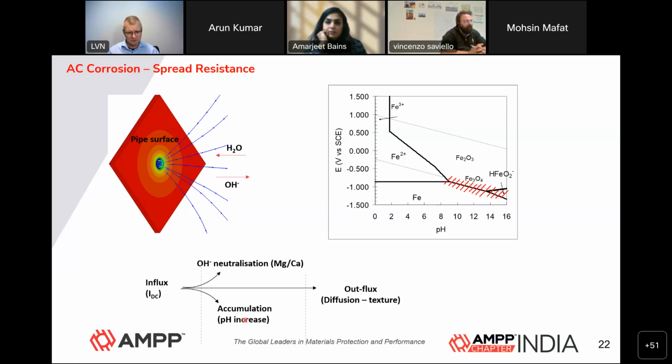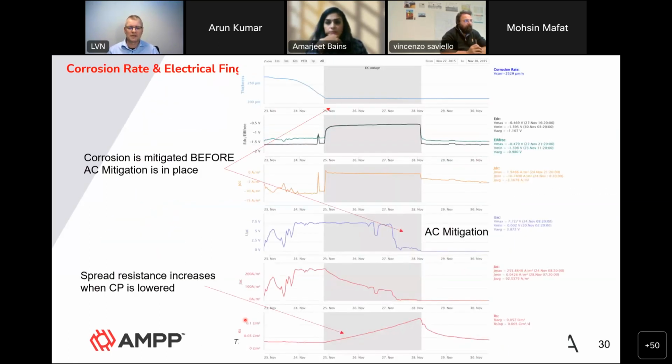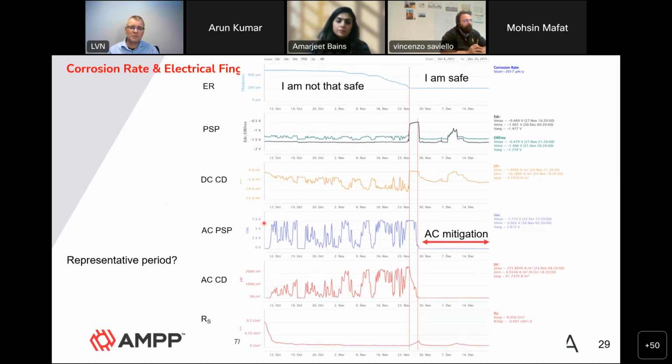So you do need to consider a grounding strategy. But all the curves that I actually showed here was at, say, 7.5 volts of AC maximum, causing a whole lot of AC corrosion, and there's no need for grounding when it comes to safety reasons here.